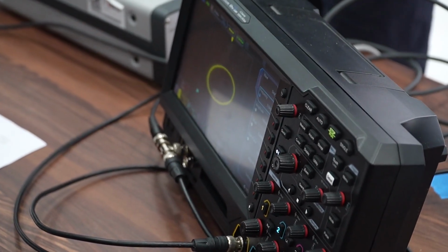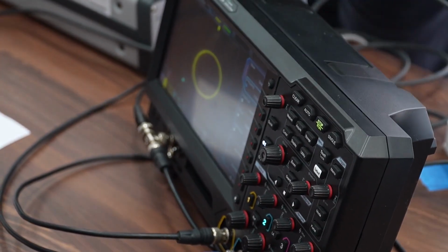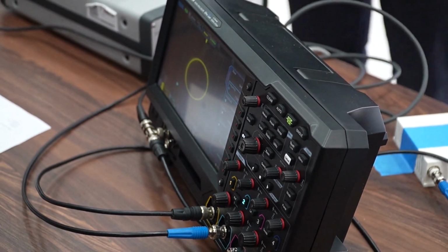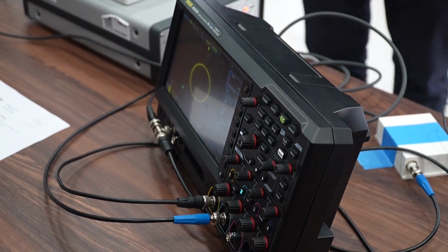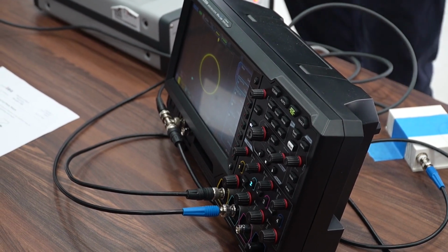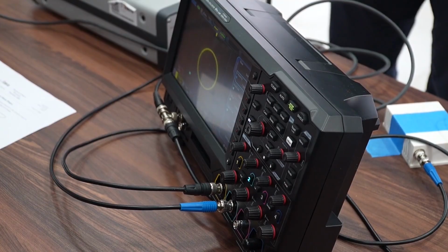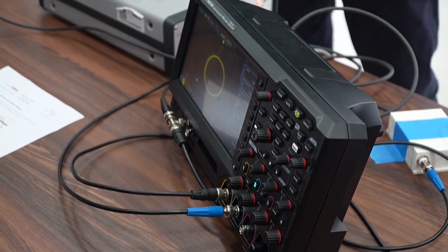And below that, same thing, the circle collapses completely. So if you're in the eigenfrequency, in the XY diagram, you should be able to see an almost perfect circle. And this is actually because the angle between excitation and deflection should always be like minus 45 degrees, and this is why you get the circle. So this is the reason behind it.